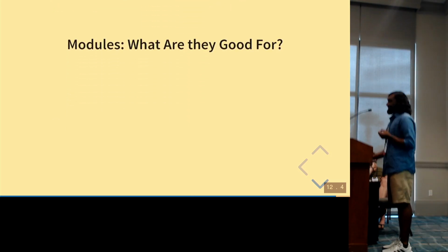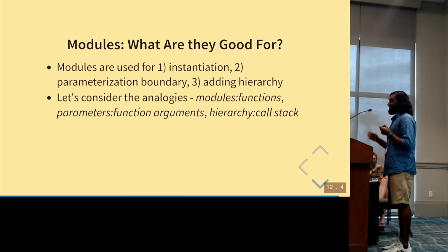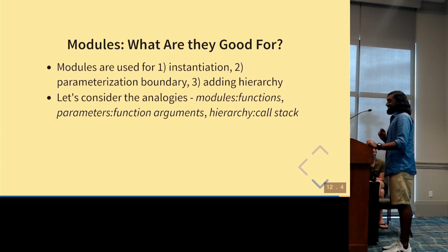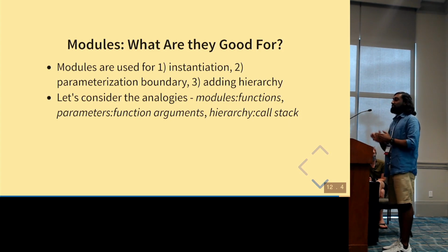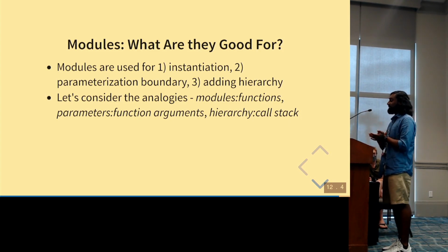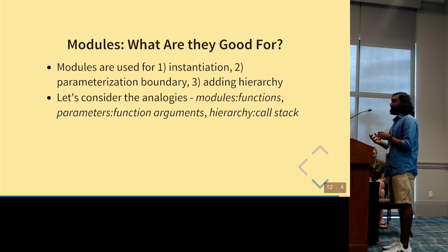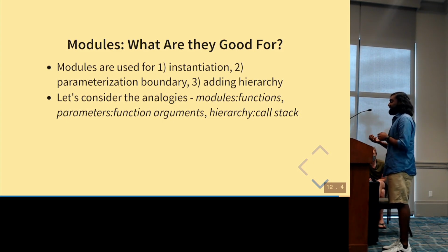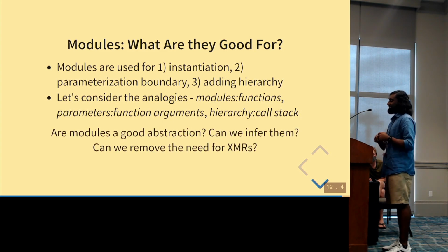The other question is about modules. What are they good for? Modules are used for three things that I can think of. One is instantiating a circuit and stamping it out multiple times. One is to establish a parameterization boundary, and the other is to add hierarchy, mostly for the user experience. So I have these analogies where we can try to treat modules as if they were functions in software, parameters as if they were function arguments in software, and hierarchy as being nothing more than a call stack in software. So with these things in mind, can we perhaps infer modules from an HDL?